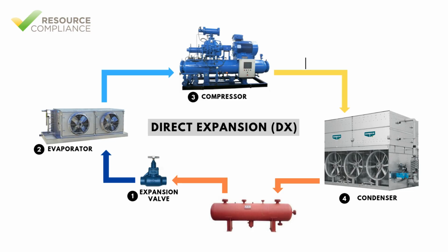A refrigeration condenser receives high-pressure superheated vapor from the compressor. As the refrigerant passes through the condenser, its temperature is lowered and the vapor is cooled. Once the refrigerant becomes saturated, it continues to reject heat, but now in the latent form as vapor transitions into a liquid at a constant temperature. High-pressure saturated liquid exits the condenser and enters a high-pressure receiver or is piped directly to an expansion device.